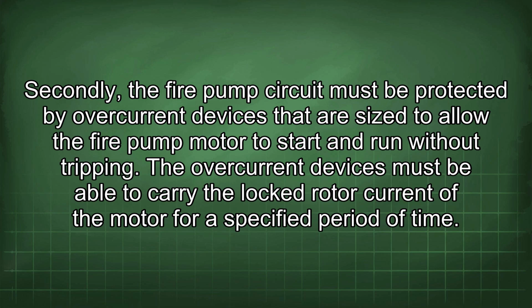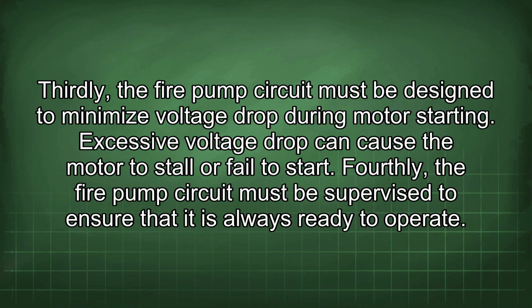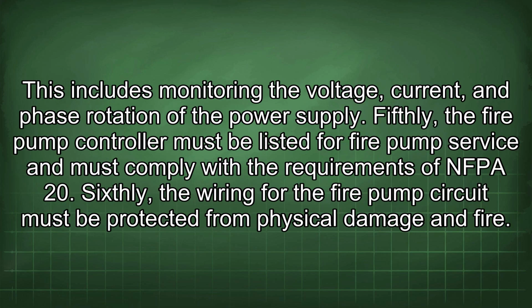The overcurrent devices must be able to carry the locked rotor current of the motor for a specified period of time. Thirdly, the fire pump circuit must be designed to minimize voltage drop during motor starting. Excessive voltage drop can cause the motor to stall or fail to start. Fourthly, the fire pump circuit must be supervised to ensure that it is always ready to operate. This includes monitoring the voltage, current, and phase rotation of the power supply.